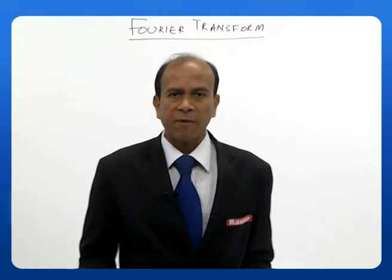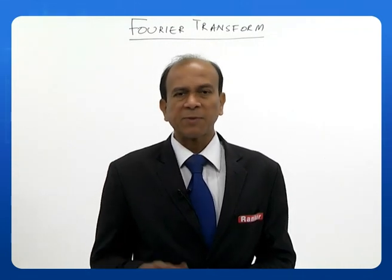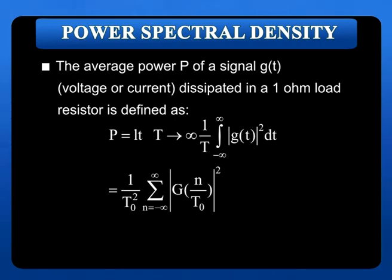Now let us look at power spectral density on similar lines as we have seen energy spectral density. So what is a power spectral density? The average power of a signal g of t, whether it is a voltage or a current, dissipated in a 1 ohm load resistor is defined as P is equal to limit t tends to infinity 1 by T integral minus T by 2 to plus T by 2 of mod g of t whole square dt. This is in fact equal to 1 by T naught square summation n is equal to minus infinity to plus infinity of mod g of n by T naught whole square. So this is known as Parseval's power theorem.